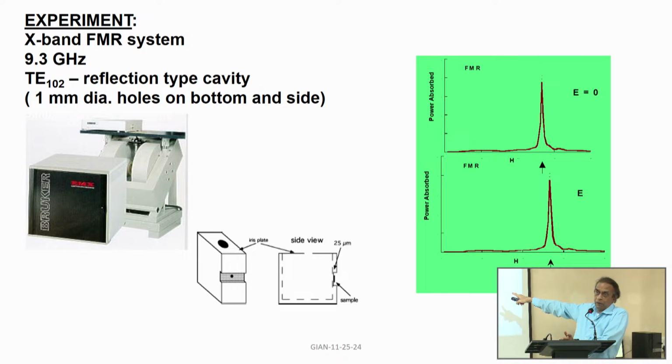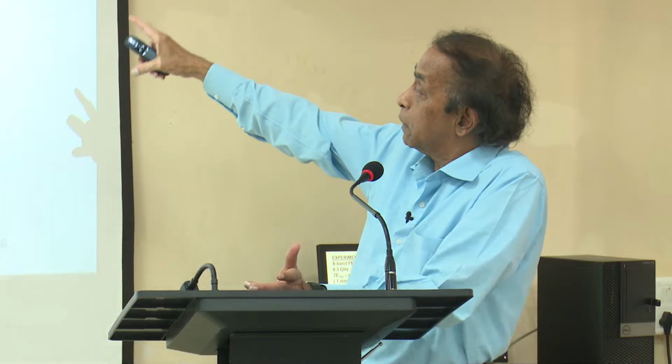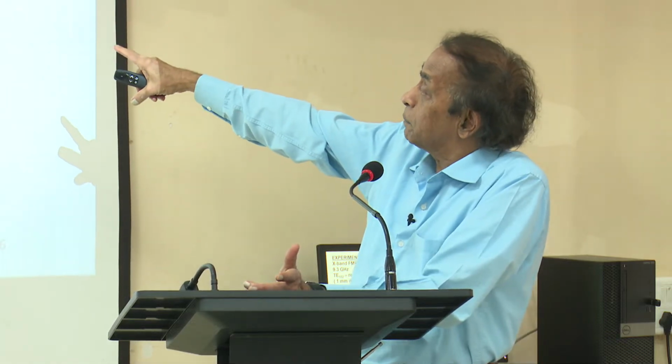That's what shows up as the spike in the power. Under no resonance, the cavity Q may be 10,000. So when it starts to absorb power, it will go down to maybe 1,000, and then the cavity will reflect more power, and that's what is seen as the spike.